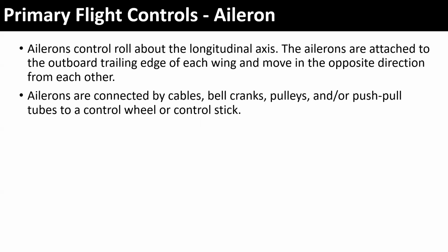Ailerons, much like any of the other control surfaces we're going to talk about today, are controlled through the same thing: cables, cranks, pulleys, and tubes that run to them. Like you mentioned, airplanes may have fly-by-wire. These may have electronic controls as you get into fancier airplanes. Now, my budget keeps me on cables, but as you get fancier airplanes, you get higher in tech. But anyway, our airplanes that we're flying for flight training purposes, every one of the ones in the hangar, they're all driven by cable, just like the elevator.